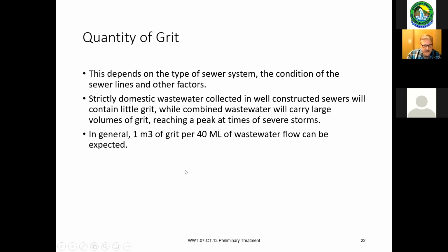Typically, in general, 1 cubic meter of grit is removed for every 40 million liters of wastewater. That's a typical design standard that is used. You may see that kind of question pop up as well.